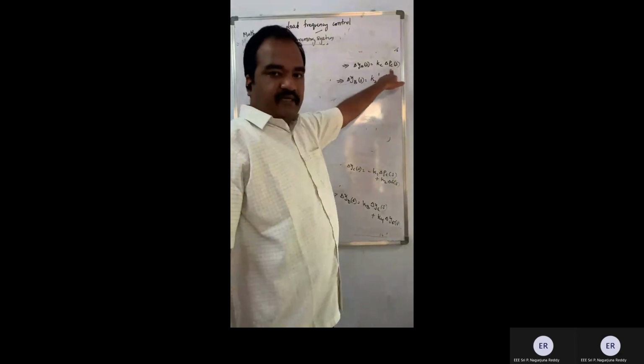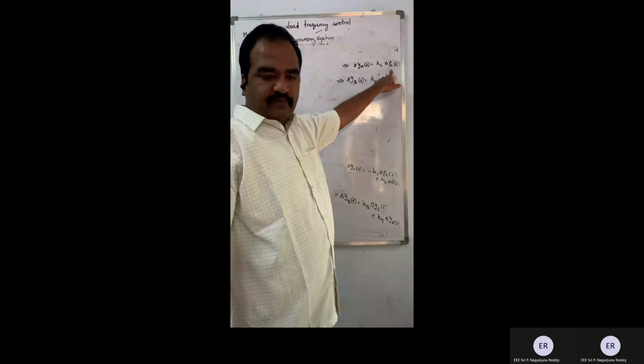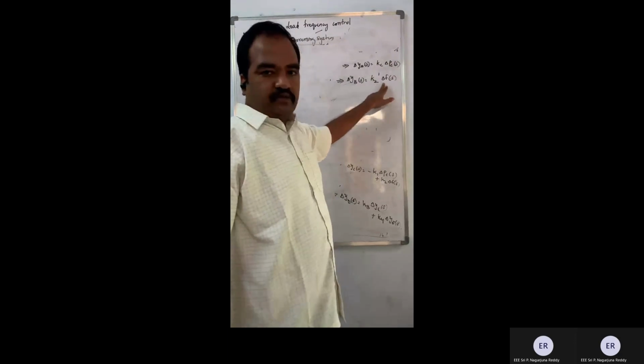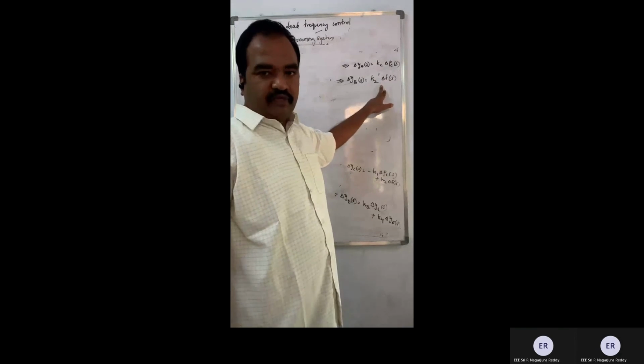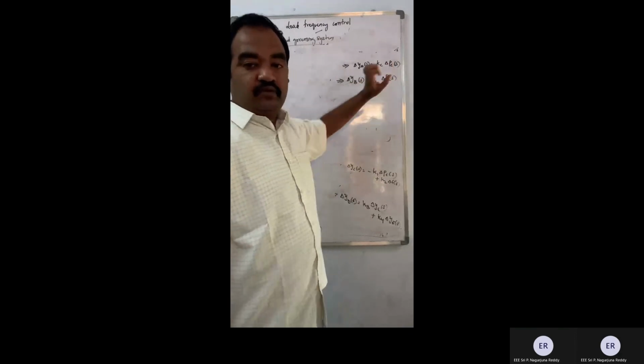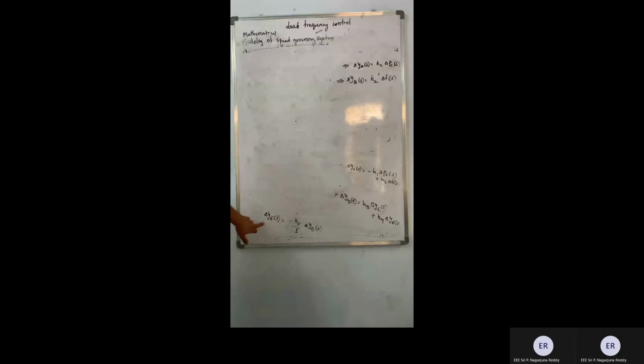Literally speaking, what are the inputs for my function now? Either I can manually change my power intake, or this is an automatic control which is happening because of the change in frequency. These two are considered as inputs, which are going to affect my steam valve setting. This is the actual steam valve setting. As you have seen, at point E, I have the main piston of the hydraulic amplifier, which controls the steam quantity to the turbine. So, I need YE in terms of Pc and f. I am going to get that equation now.